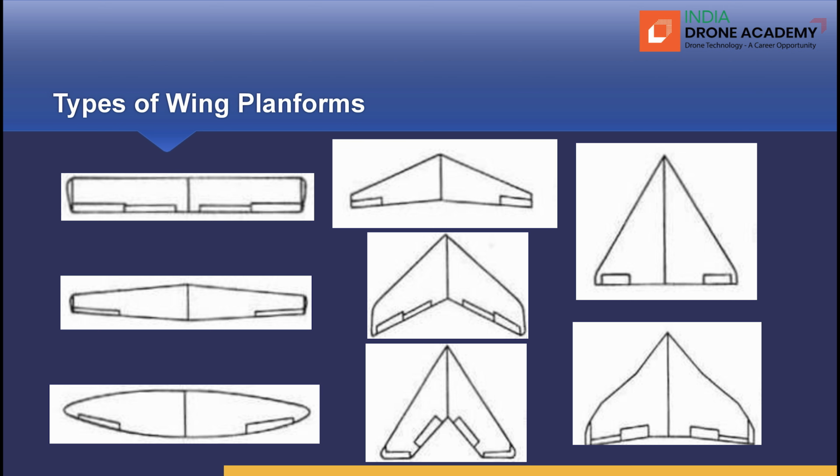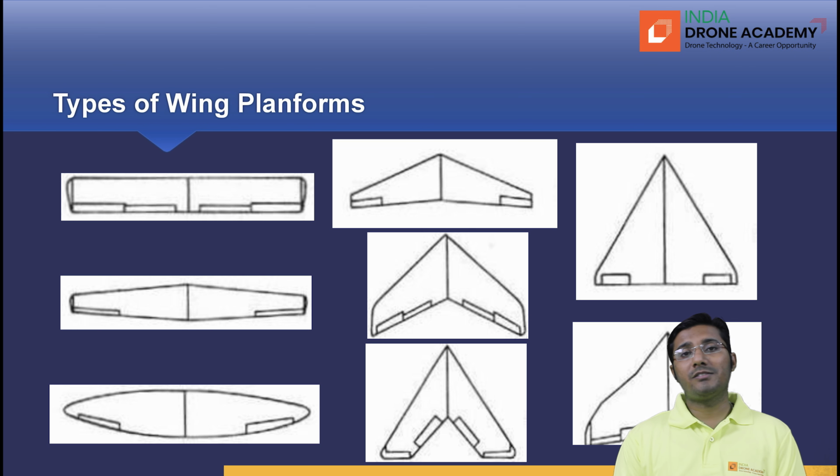Aerodynamic efficiency means L by D ratio. So, like elliptical wing has a very good distribution of lift on its surface because of its shape. But there are again some other wings which are available, which may not offer very good lift distribution, but they are good to fly at higher speeds, like swept back wings or delta wings.